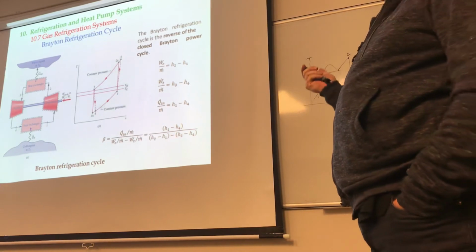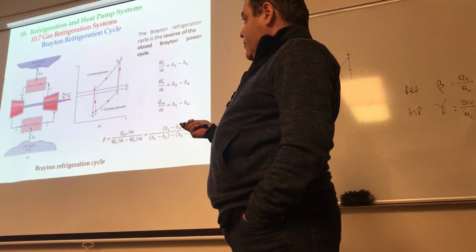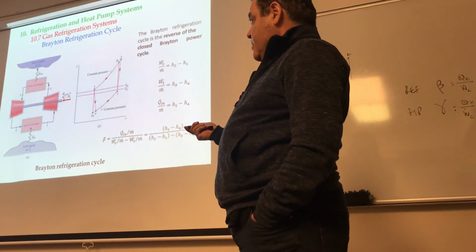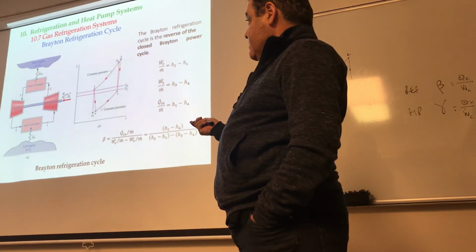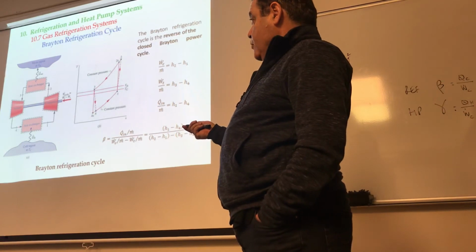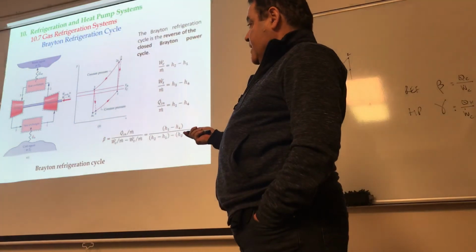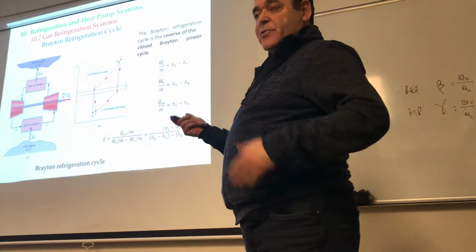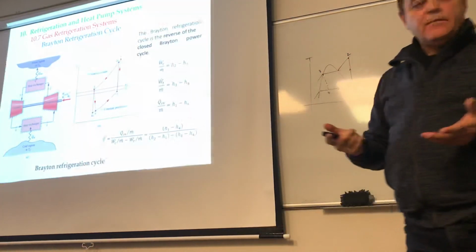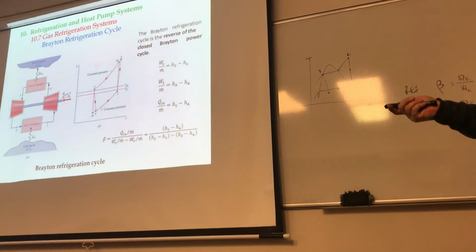Anytime you need to go back when you have a fluid like air, you expand through a turbine, one stage, come back to the lower pressure, and you do it isentropically, you come back to state 4S. And then what happens? Now you have low pressure, low temperature, right? As it passes again through this heat exchanger, it absorbs heat from the cold region, okay? So you have one space in which you are losing heat, and in the other one you're extracting heat.